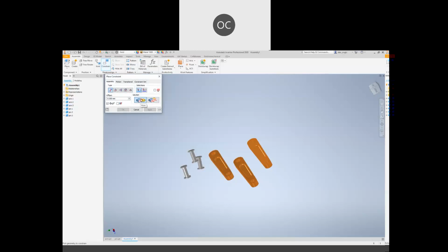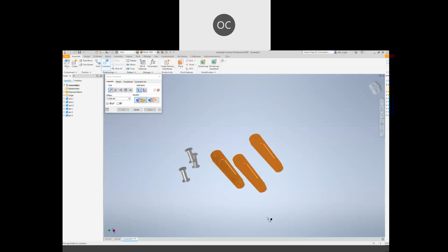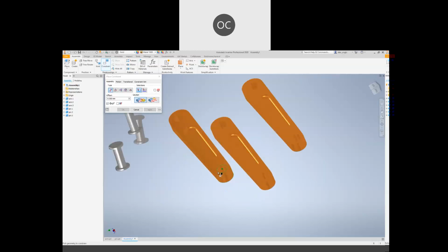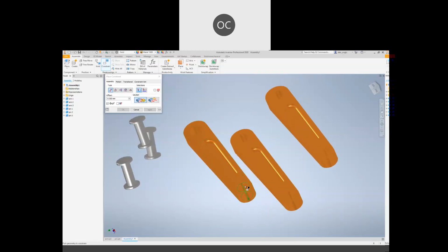So the first thing that we ought to do is we are going to mate holes and holes, center line holes and holes. So I do this one first, maybe to show to you. Please have a look. If you go to holes, you will see the center line. Click on one, and then I would like to mate with this second hole, center line also.